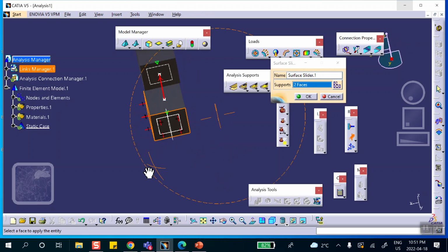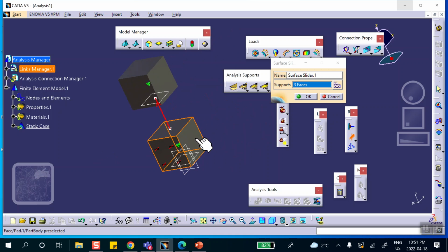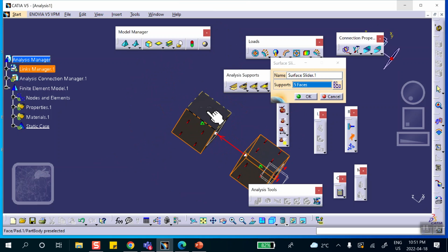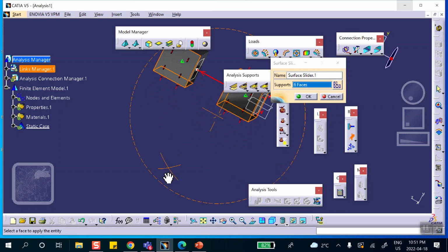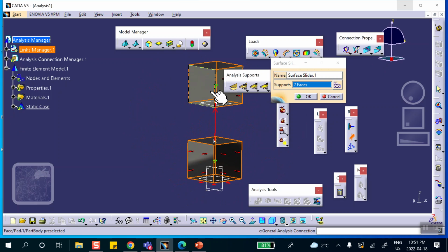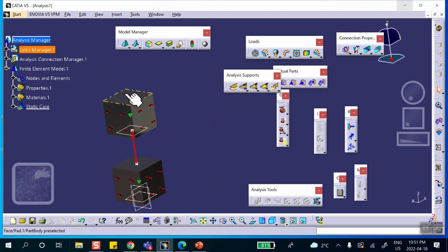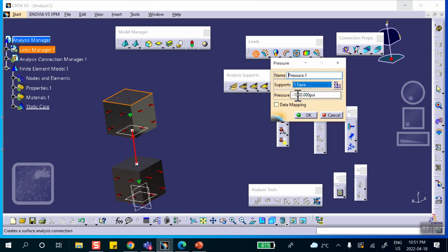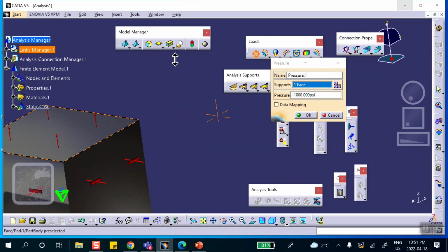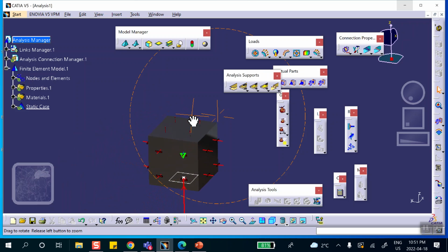And all these side faces are going to be clamped. Not clamped, roller, surface slider. This will give you an idea, assuming that I understand Paulo's question correctly, of what to do with your own problem, or he can figure it out. Say okay. And finally, there is a pressure there, pressure on the top. So pressure of 1,000, right there. Negative 1,000, that means outward. See that? Outward, upward. Say okay. And I think that's pretty much it.